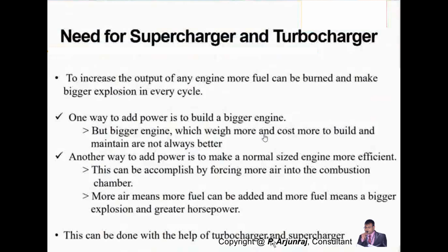I told you the cycle is the repetition of one complete stroke sequence: from intake, then the compression stroke, then the expansion, the power stroke basically, and the last one is exhaust. This forms one cycle. You need to get the power output of the engine each and every cycle. It is not that you are going to stop your power output after 3 cycles or after 5 cycles. But this should happen throughout your lifetime, till your vehicle gets stopped or your engine is in stopping condition.